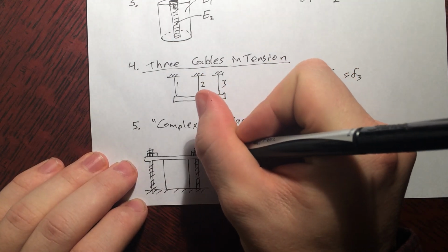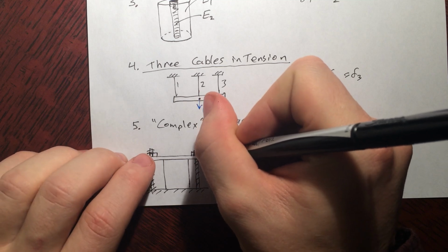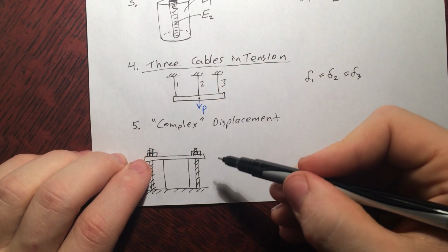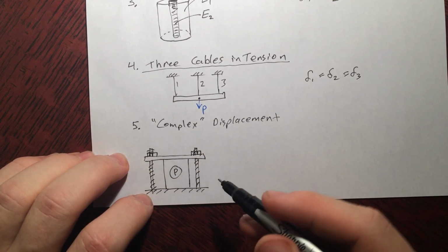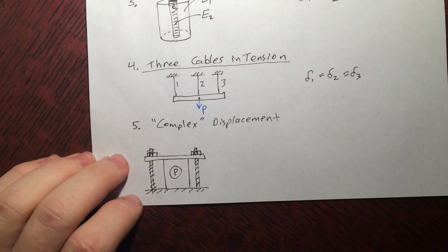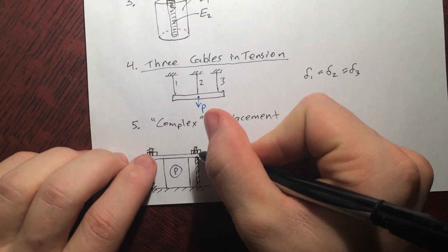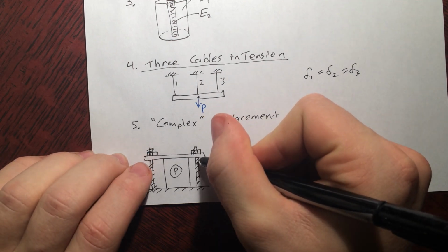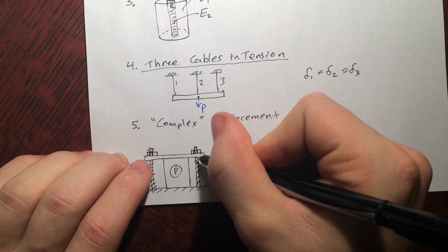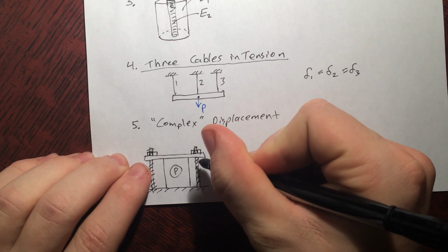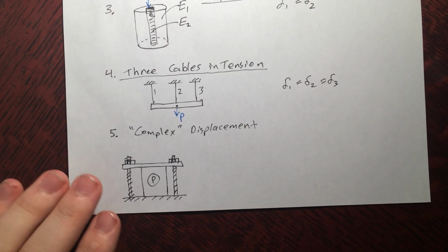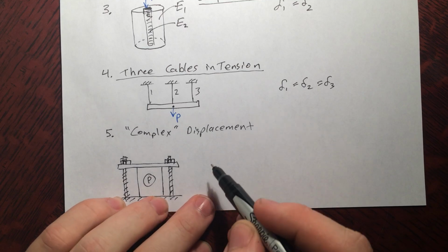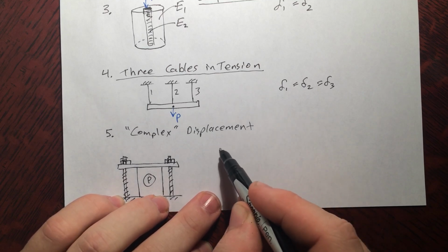So basically what happens is when you tighten these bolts, this plate moves down, but as it's moving down, it's also being pushed up by this piece of, let's just call it plastic here. So the amount that these nuts turn down is not going to be the displacement, because this is pushing back up, thereby stretching those threaded pieces of rod. So the best way to visualize this one is to draw a very good before and after picture.